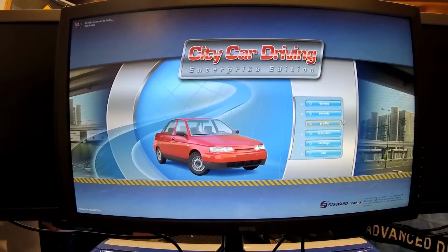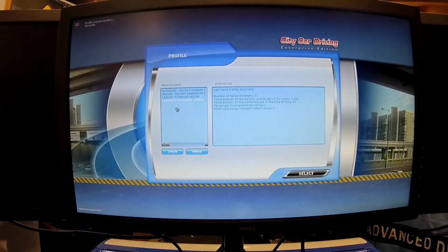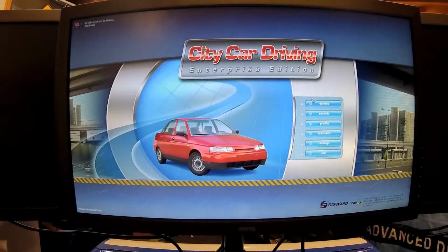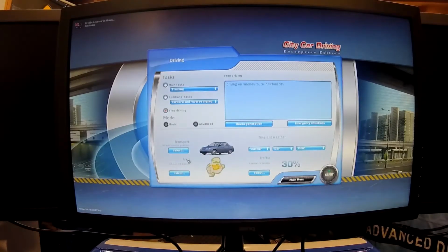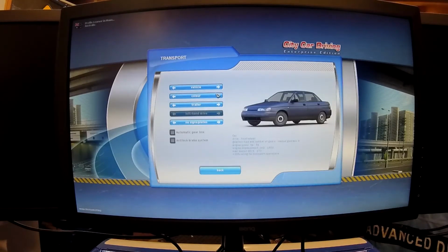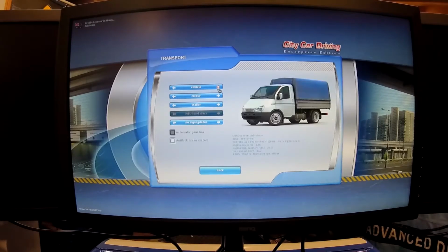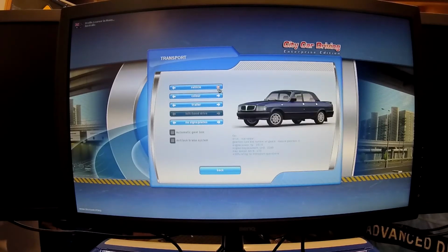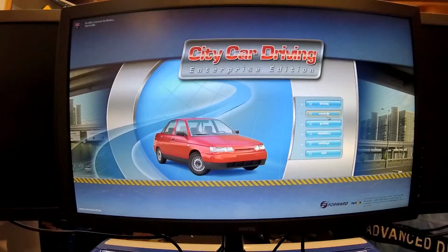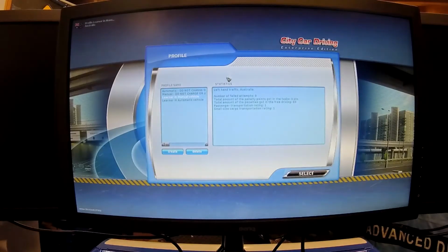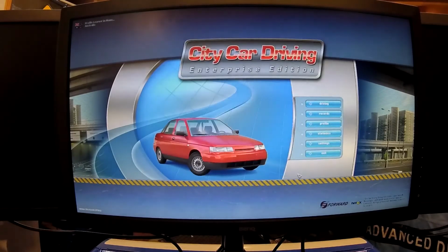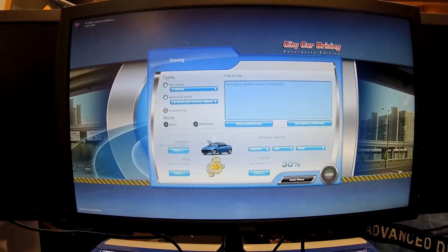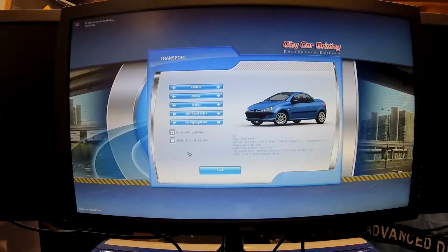A common mistake here is that you have a group of people gathered around the simulator. You are using an automatic profile and an automatic vehicle, then a new driver wants to drive and wants a manual transmission. If you change to a manual vehicle while still in an automatic profile, some of the gear stick positions will be assigned wrongly. This also applies if you're using a manual profile and driving a manual vehicle, and then a new driver wants to drive an automatic vehicle, and the instructor does not change the profile to an automatic mode.